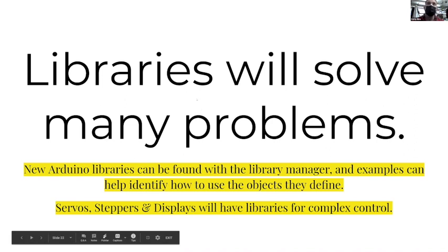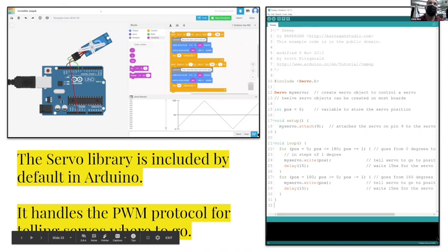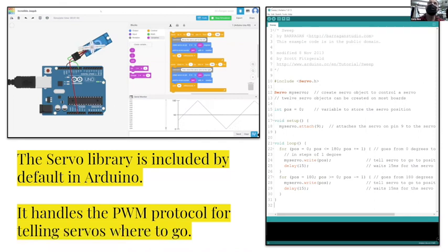The Servo library is built into Arduino, and so Servo Sweep, if you go to File, Examples, Servo, Sweep, which I've just memorized at this point, you can use the standard Servo library, and here's your 30 lines of code that'll get your servo to go back and forth. I've just recreated it in Tinkercad, made it into a GIF. And so here's this servo moving back and forth. It's sliding along, and all of this is handled by a library.